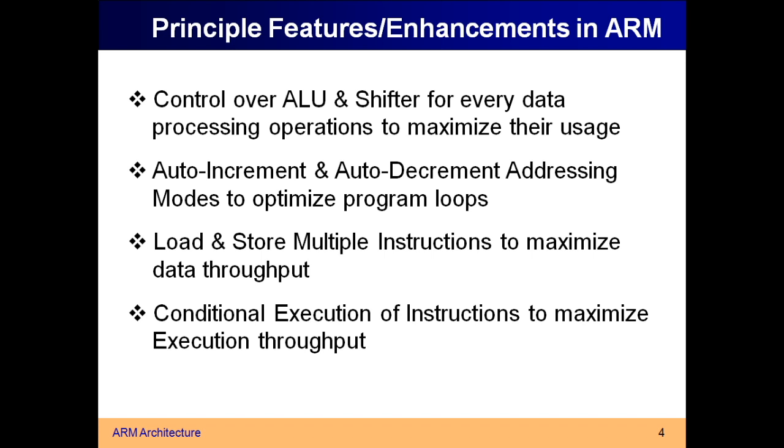So load store multiple instruction, what does it do? It can load as well as store multiple register content or memory content to and fro. In the normal RISC machine, you can only load or store one register content or one memory content, but here you can load and store multiple register contents by using a single instruction known as STM or LDM, store multiple, load multiple.